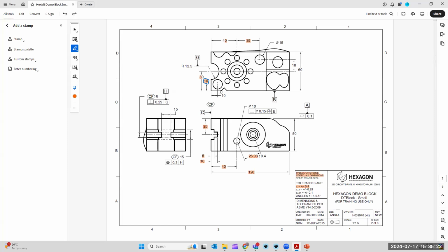So if datum B is our origin, or actually it's kind of datum A, B, and C, if you think about it's on this corner, then it's logical to think that an A, B, C alignment is probably a good starting point for this tolerance, this tolerance, this tolerance, and many others, right? So we can probably do an awful lot of inspection with an ABC alignment. And it's what we did in our manual. So I'm going to suggest that we start with an ABC alignment and inspect everything we can on our drawing with that alignment.